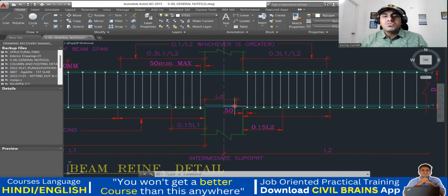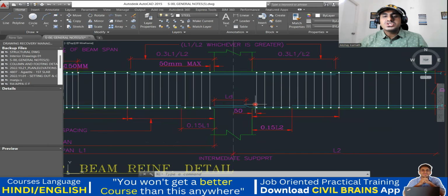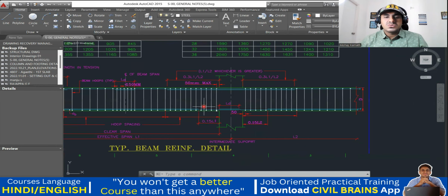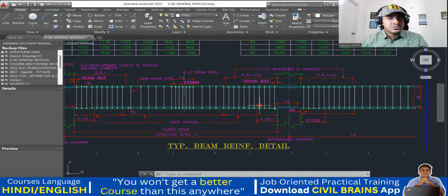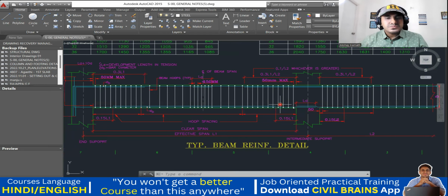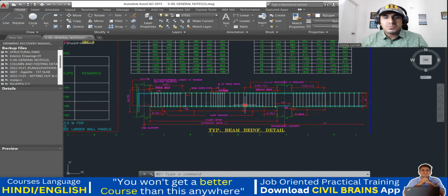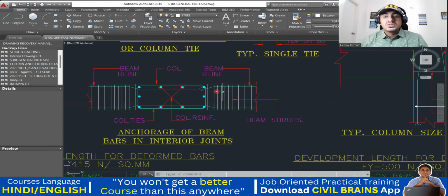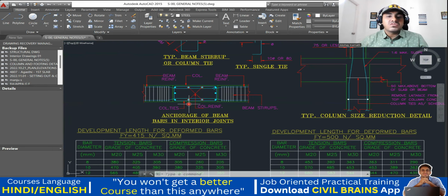And then whenever you're lapping the bottom steel, make sure you're lapping your bottom steel within L by 4. But if you're lapping at a column and a beam junction, always good. And you have to lap it like this. Okay, you have to lap it like this. I think everything I've explained here, so most of the things are done. Then this one thing is left out.